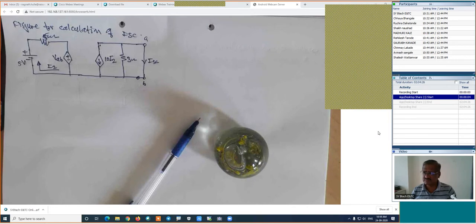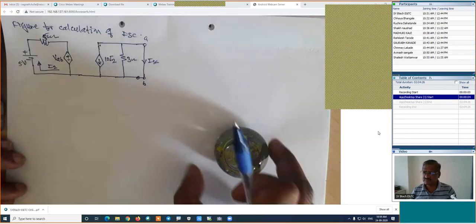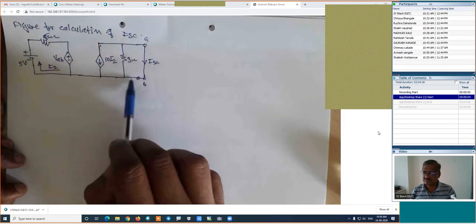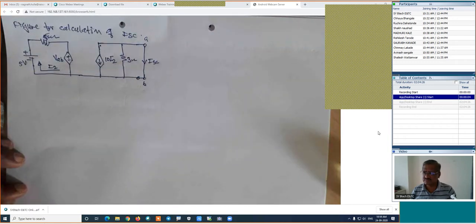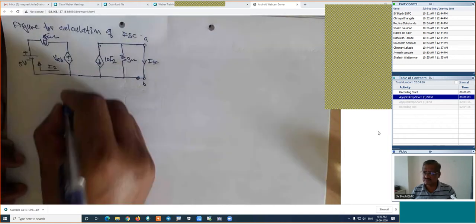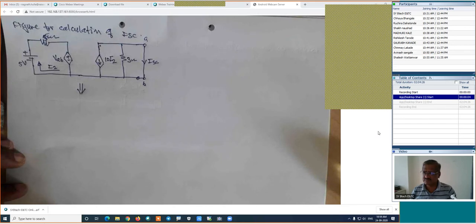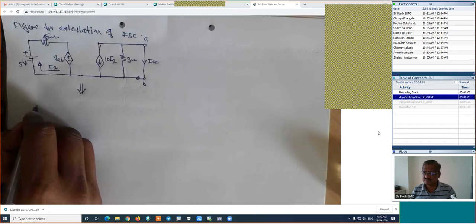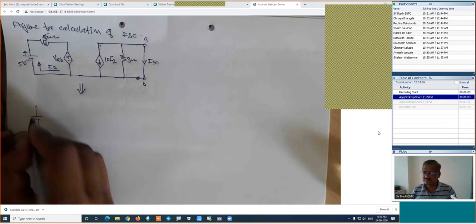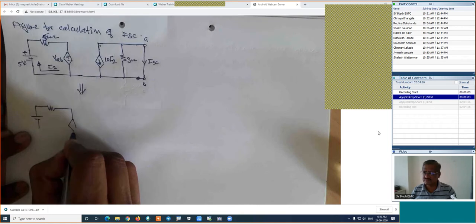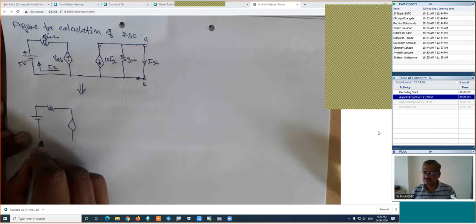Okay, fine. Now look at here, how will the procedure be? Look at this short circuit. This short circuit is parallel to this 3 ohm resistance. Is it right? First, I will draw its equivalent circuit, because many times whenever we have a short circuit parallel to any branch, the better way is to modify the circuit and then work out the calculation. This will be the figure for the next calculation, because I am modifying this figure.